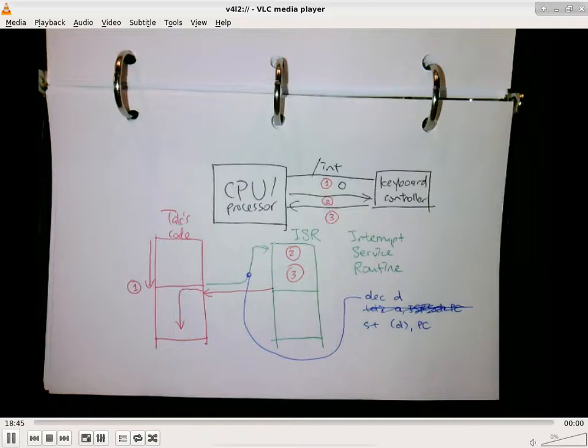So this is why, in general, not the toy processor, but in general, you cannot assume locations below where the stack pointer is pointing to can preserve their values. You basically have to assume that if it's below what the stack pointer is pointing to, that content can change without your code noticing. So don't count on it being there. Do not count on it.